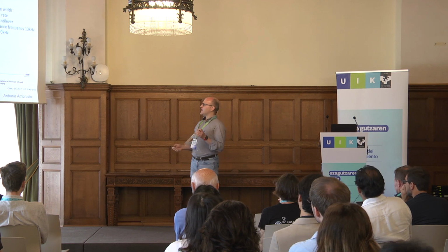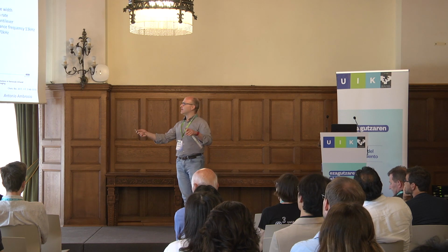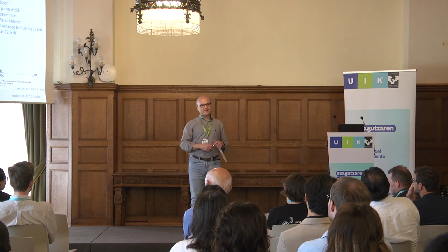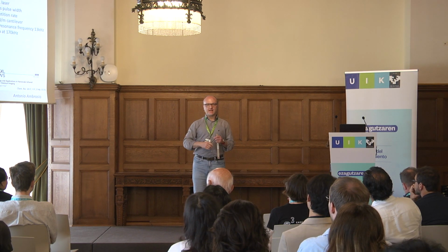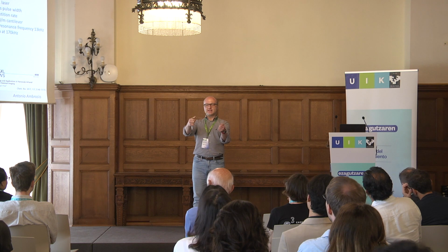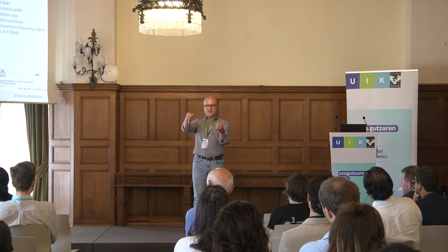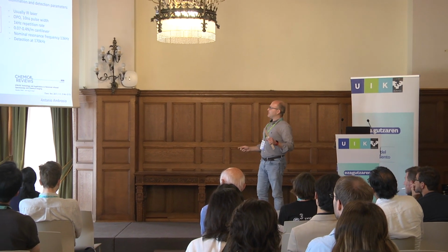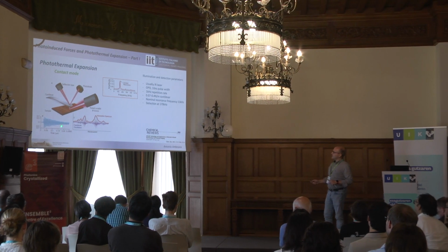Now, if you shine a laser, no matter how, with a lens, with the parabolic mirror, to this gap, and then you start to go on and off, right? With the laser, what you can do in this cantilever in contact, you start to excite the oscillation. How? Well, let's go in order. What happens in this picture, at least, in this photothermal expansion?